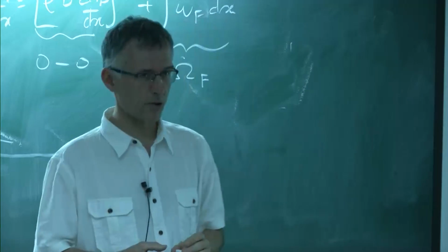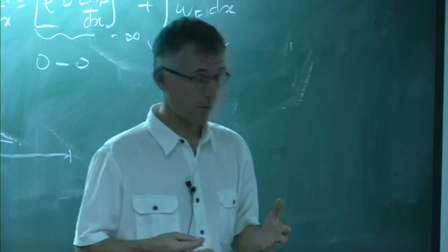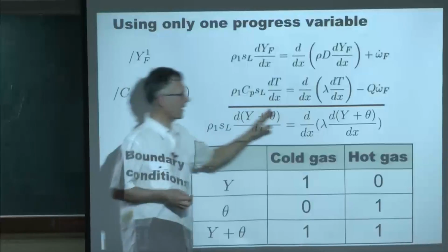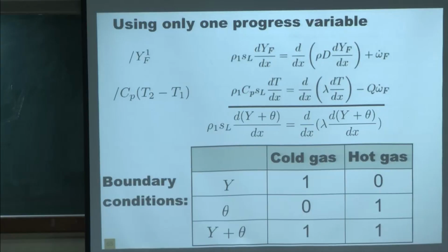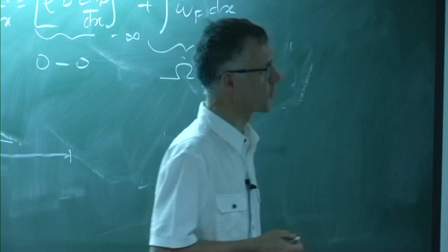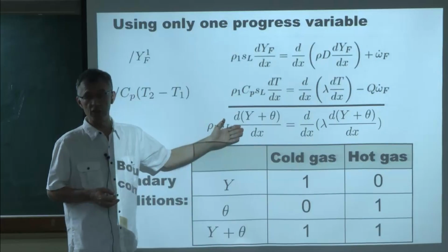You know that in combustion, our main problems come from reaction terms, from these source terms. So every time we find an equation which has no source term, we're very happy about it, and we call it a passive scalar. We'll see that again today. Passive scalars are very convenient quantities because we can solve for these equations. Actually, this one is extremely easy to solve for.